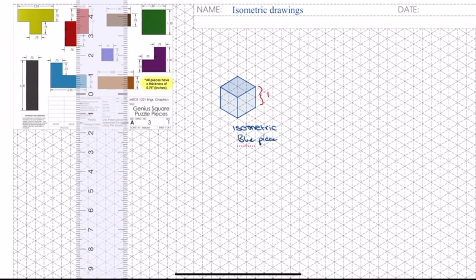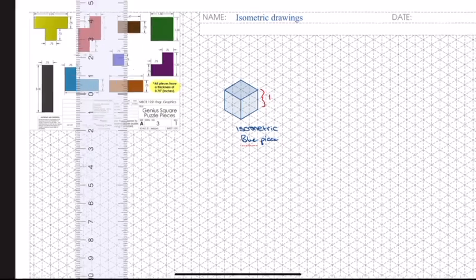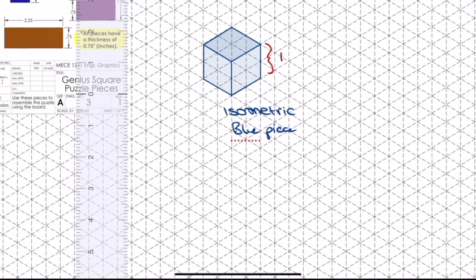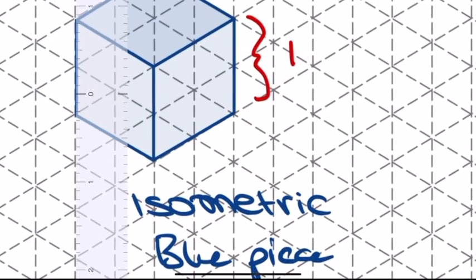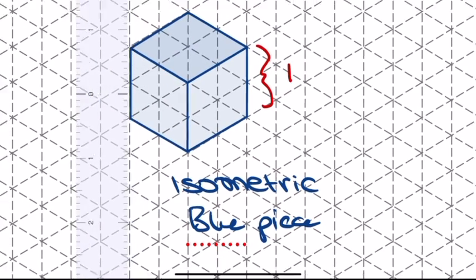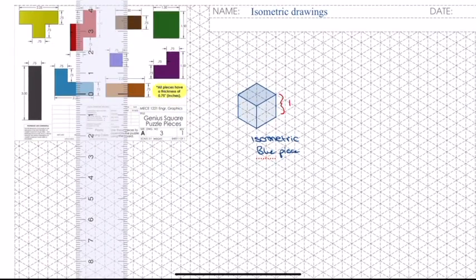So that's the isometric. So let's do an oblique now, and let's keep the same unit. So once again, I'm saying that 2 of those little lines are 1 full 0.75. So let's do this drawing in the oblique. So this is the oblique drawing, oblique paper. Notice how the lines are now 45 degrees in angles. So once again, for this one, it's easier to draw because the front face does look like the front. So this is my front face, right? It does look like a square, so it is drawn like that.